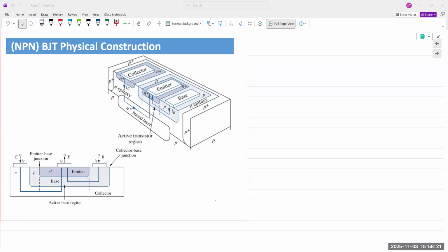Okay, and that in short is also how amplification works. You inject a small amount of input into the base, but a large amount of carriers are coming from the biasing, meaning from the emitter, and then those electrons or the holes that are flowing out will take on the shape of the input base current or the base voltage. That's also the basic functioning principle of an amplifier.